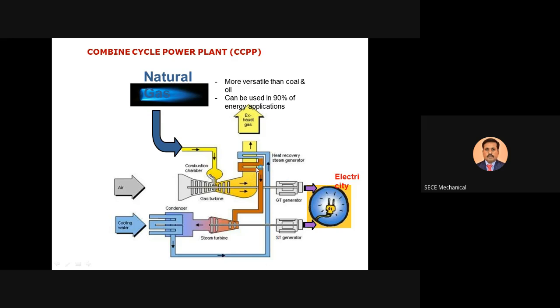In the water tubes, the hot gases pass over them. So the water gets heat and finally gets converted into steam with the help of this waste heat. Here you can see how the steam goes to this generator, indicated in brown color. So automatically water is converted into steam, and that goes to the steam turbine.